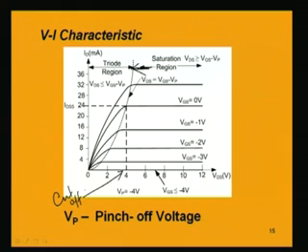And one important thing, as we have mentioned, is that VGS cannot be positive. So, we do not have an enhancement region as we have in the depletion type MOSFET. The depletion type MOSFET has two regions, depletion as well as enhancement, but the JFET does not have the enhancement region, meaning we do not have the region where VGS is positive, that is not possible.